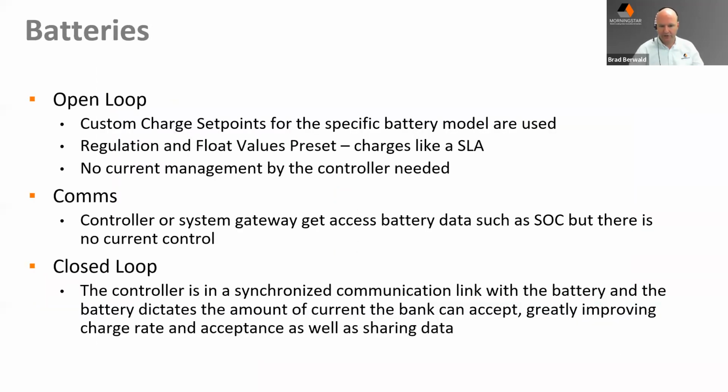And then one additional note on that is when we talk about these presets, that applies to all of Morningstar's products. What we call an open loop is just the charging preset, where we change the settings and we charge a lithium battery sort of the way we charge a lead acid battery, with the right settings and accommodations made for it. But going forward, you'll see a lot more batteries have the addition of comms, where they have some communications and you may be able to get data out of that battery, but the controller is still really just charging the battery posts using a preset profile.